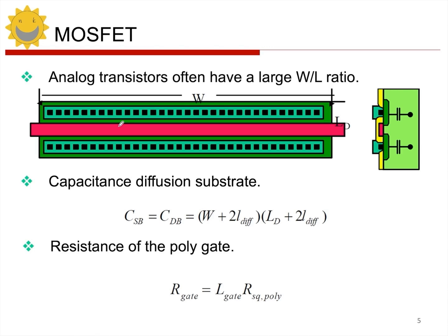But the problem is, usually the design rule does not allow you to do that. If you draw a contact on top of the gate, it is a sensitive structure and will affect the electrical characteristics of the channel. So if you draw a contact above the gate, it will usually throw an error when you run DRC, which means you can't do that. Since I can't draw contacts on the channel, I can only place them outside the gate, which means at the two ends, right? In this case, that doesn't solve the problem we just talked about, right?